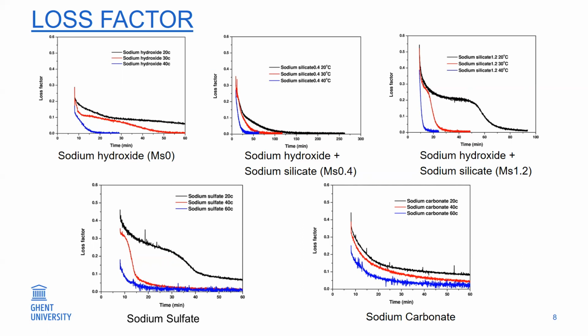On the other side, C-S-H links and bridges between the slag and fly ash particles are enhanced with the progress of the reaction. As a result, the rigidity and stiffness of AAC paste suspensions are consolidated, showing a gradual increase in the storage modulus and a reduction in loss factor. With the elapse of resting time, the loss factor reaches a steady value, reflecting the transition from viscous behavior to elastic behavior, which we call the elastic state.